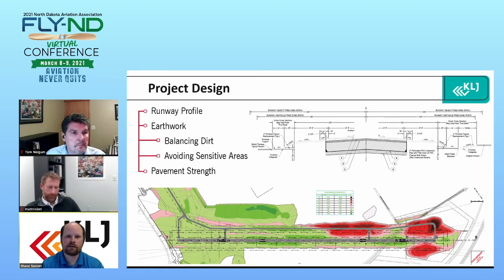When we looked at chemical stabilization, blending in lime or cement, versus mechanical stabilization, the recommendation of the geotech engineer, and what we ended up going with, was the mechanical stabilization route, where when we got to those soft areas, we did an additional 2 feet of subcut.